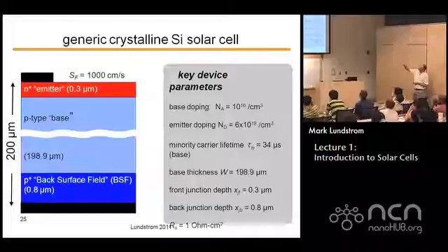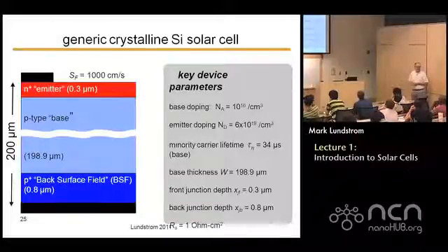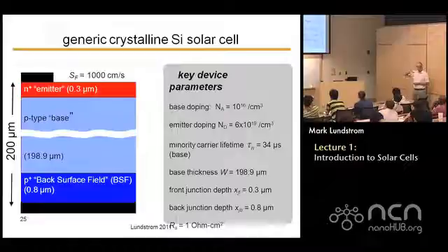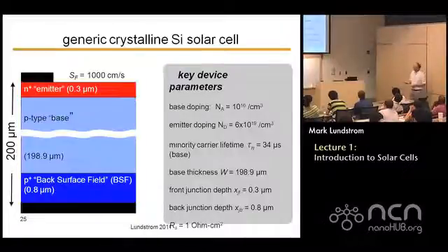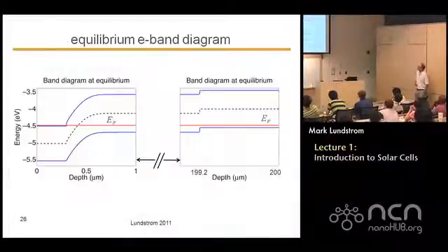And I can't put a metal contact across the whole top surface, where I wouldn't let light in, right? And I'm trying to make a solar cell. So there's a metal grid of fingers, and you try to design the grid such that you obscure less than 10% of the area with the metal grid. If you get it too fine, you'll start adding some resistances and things.